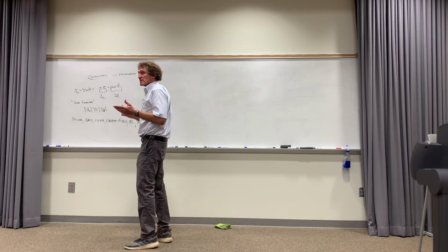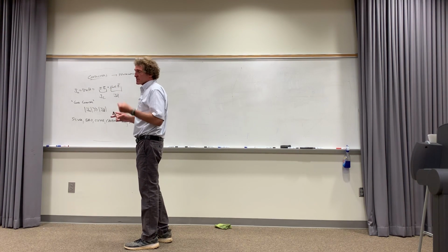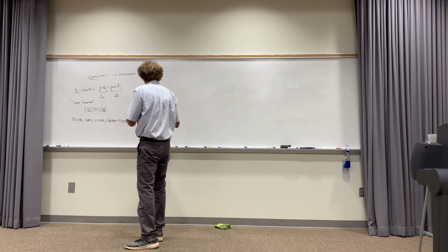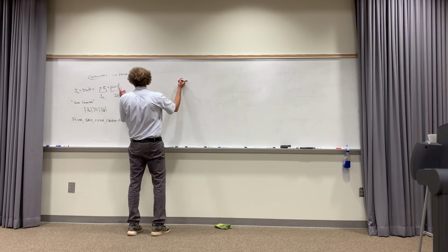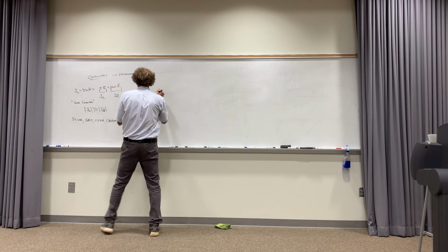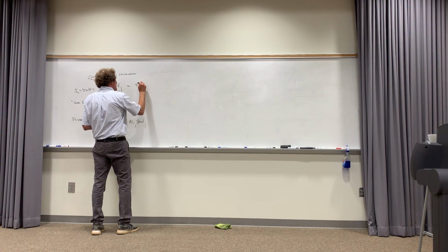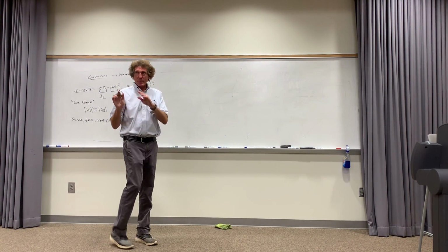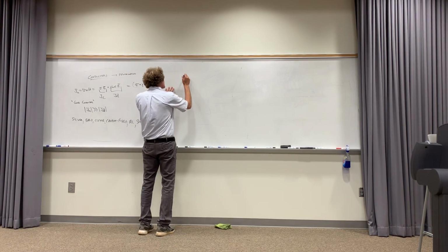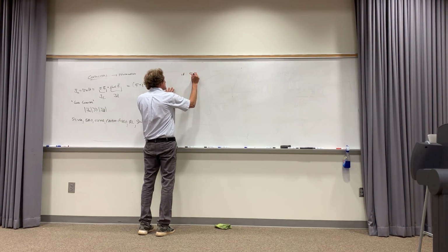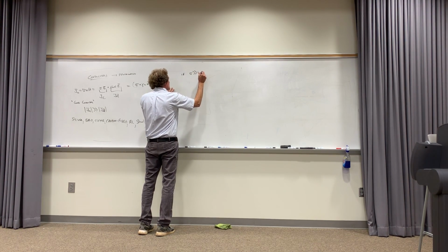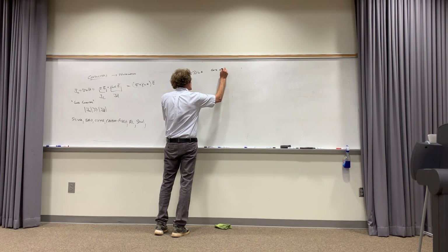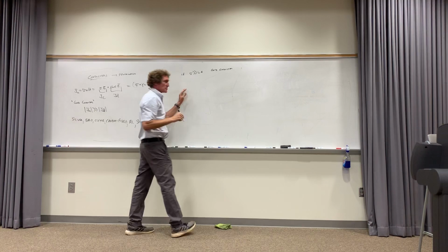So how do you really determine if something's a conductor or not if you were just given a piece of material, and I say, do this assessment? Well, if you look at these two, really what we have here is sigma plus J omega epsilon working on E, right? And the good conductor depends on the frequency, remember that. So if sigma is much greater than omega epsilon, then it's a good conductor. That should make sense to you.